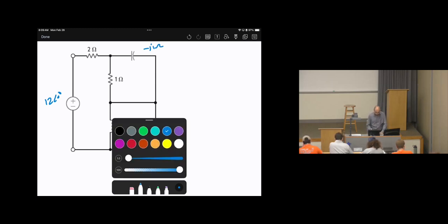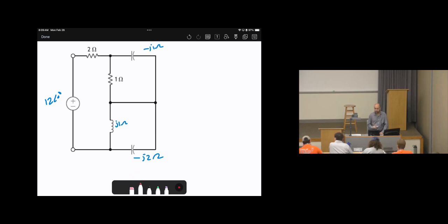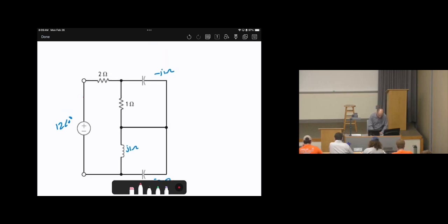So according to the procedure that we know from DC circuits, we can apply it here, which is to label all of the current directions and all of the voltage polarities. So we will assume a source current going out from the positive part of the source. And don't forget to put a bar above this quantity because we are dealing with complex numbers, it's phasor domain. If you didn't put the bar, then it will be similar to DC. It's not DC, it's AC. But again, we will make it similar to DC by using the phasor domain. So it's very crucial, very important to put the bar above the symbols.